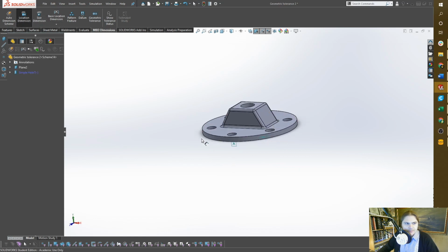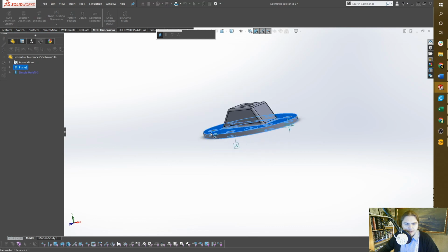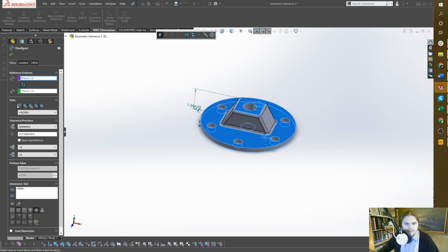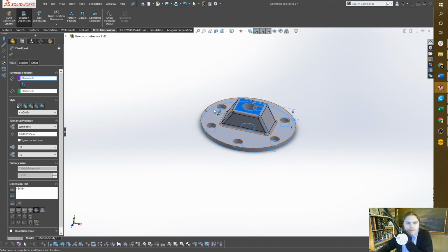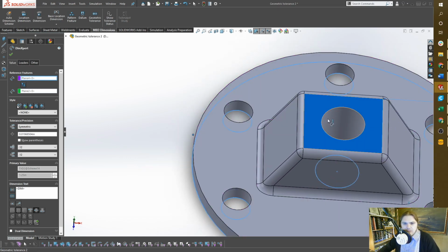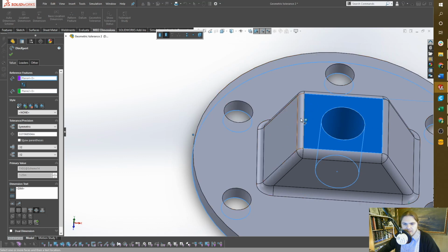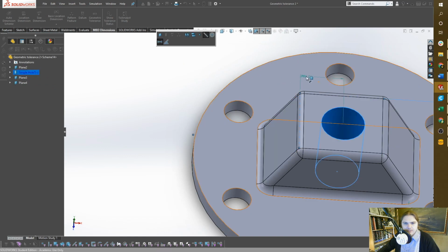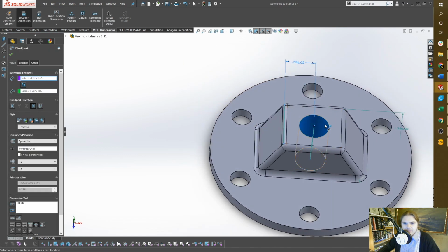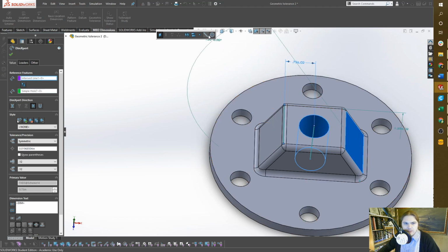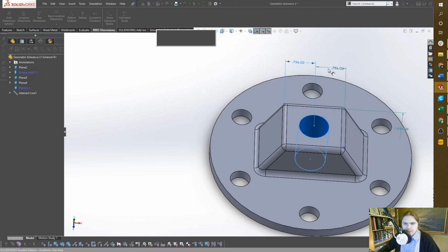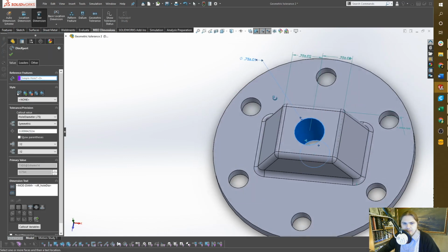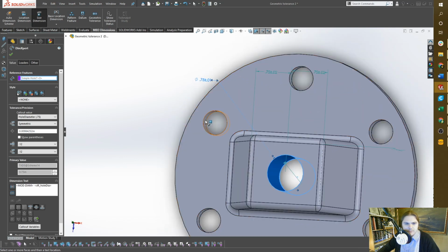Okay, so a couple of the basic things first. Let's get the thickness of the plate with a location dimension up to the very top of this. We'll do it from datum B to the intersected edge here. So I'm going to click on this inclined, click on intersecting line, click that surface. Place that. Do the same thing for the other side. Check and place it. Let's do some size dimensions for that, and then our patterned holes.